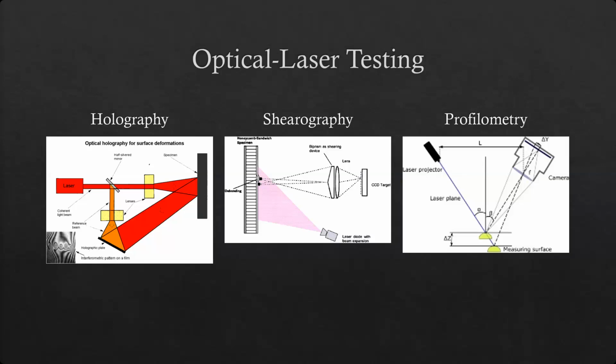Whereas with something like a profilometer, you can scan. Otherwise, you have to measure each dent. How deep is it? How big a diameter? What's the width versus the diameter? How close is it to every other piece of structure around it? Ribs and stringers and frames and formers. How close is it to other dents in the same area? Is it in an area that's critical for things like airflow, like pitot-static, or things that could cause oil canning due to pressurization?